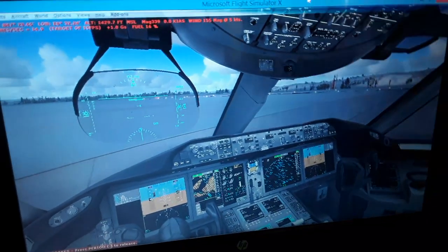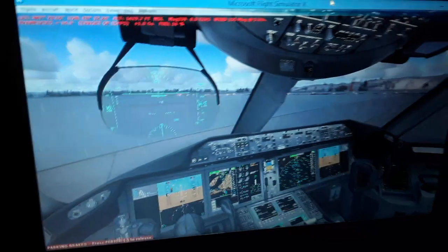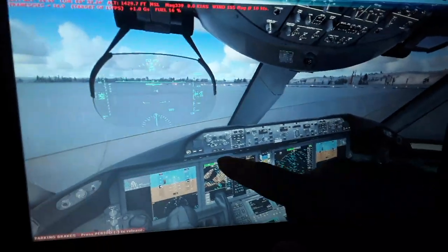Also in the navigation display, you can see the horizontal and vertical profile of the terrain. Around you can see the terrain displayed with red, green and yellow, or magenta and amber indication colors. You can also see the lakes, the rivers and the sea displayed in blue.